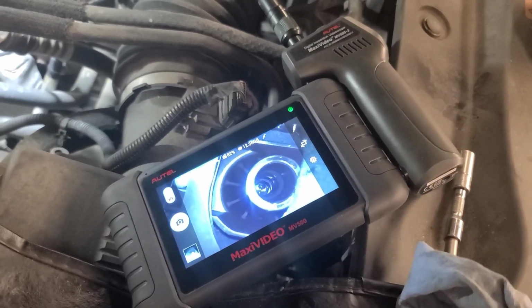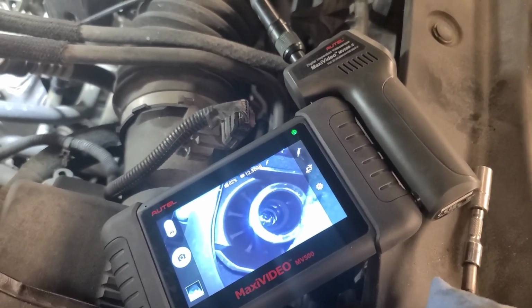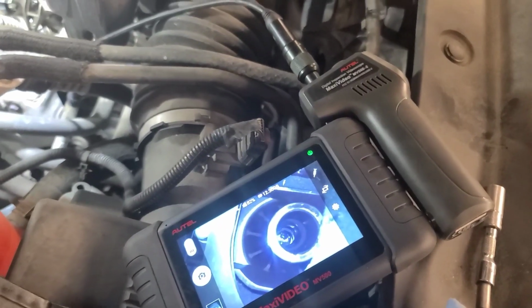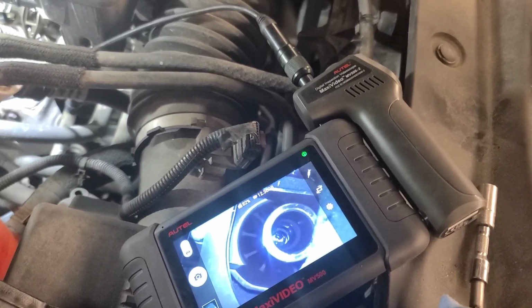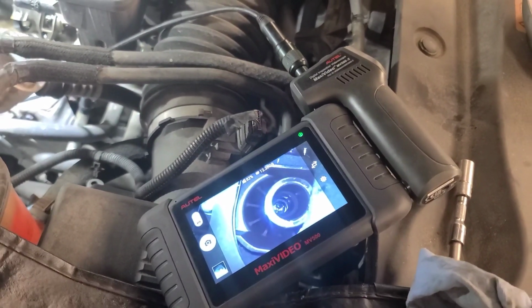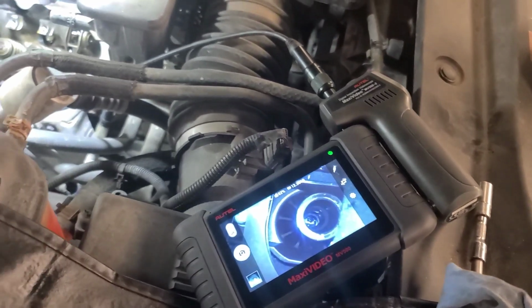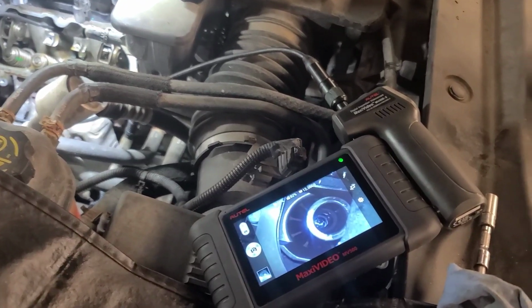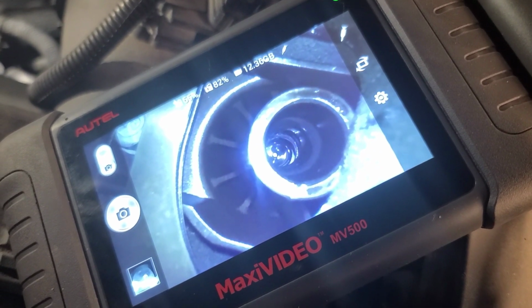There is a way to release the lifter, but that only works up to 2013. After 2014 you can't pull the management system off from under the intake plenum without pulling the fuel rails and the fuel injectors out. Now fortunately I did have these out a few months ago, but still I'm not sure if that lifter's turned in there or if it's just collapsed.